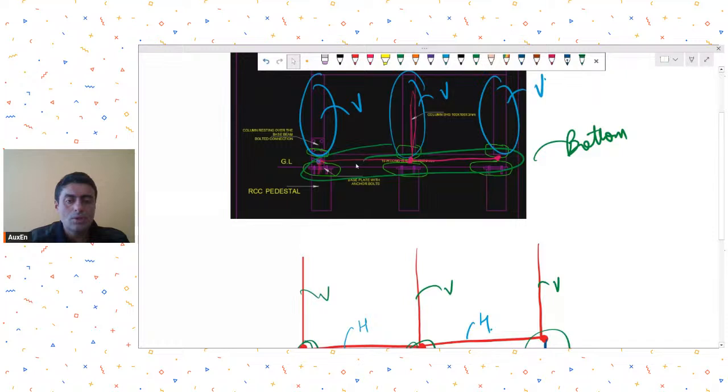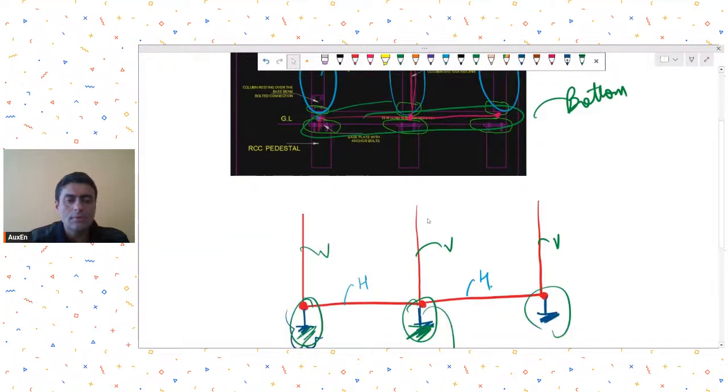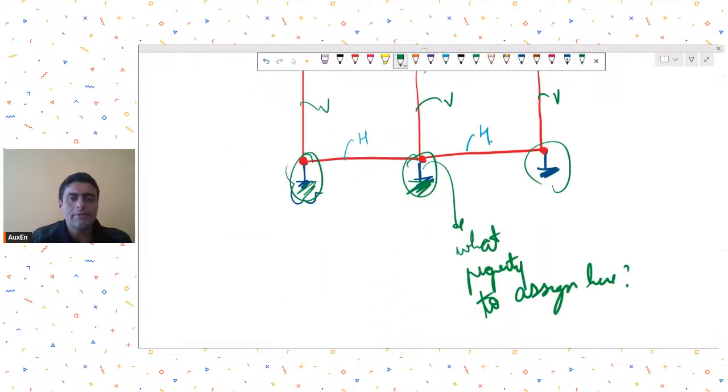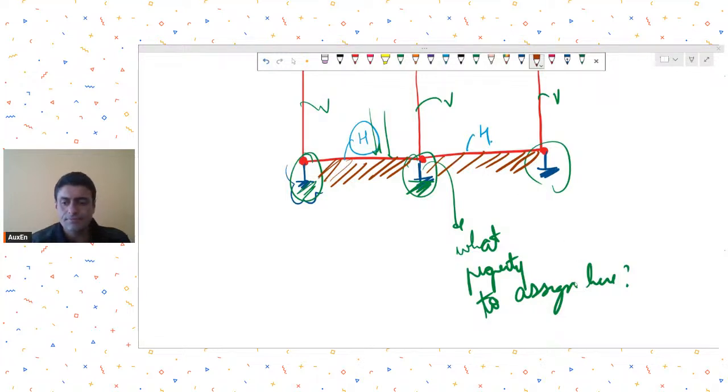Here you also need to understand whether this horizontal member is going to be loaded or not. Is it going to be loaded, or is it going to be completely rested on ground even though it's loaded? You first see whether it is going to be completely rested on ground or not. If it is completely rested, I would say there is no need to even model this horizontal member. Then you could locally do the checking.